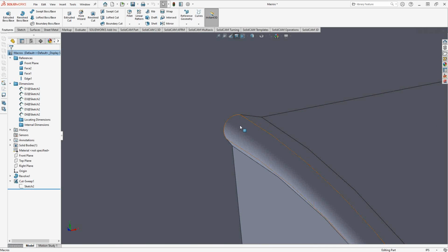If the placement of this undercut should be a little different relative to that edge. If I leave these dimensions here, then I have the ability to modify them when I go and use the library feature. Otherwise, I can just drag and drop these into internal dimensions, and then they just become hard-coded. The user of the library feature won't be able to modify my sketch for their particular purpose. So here, I'm just going to leave these here.